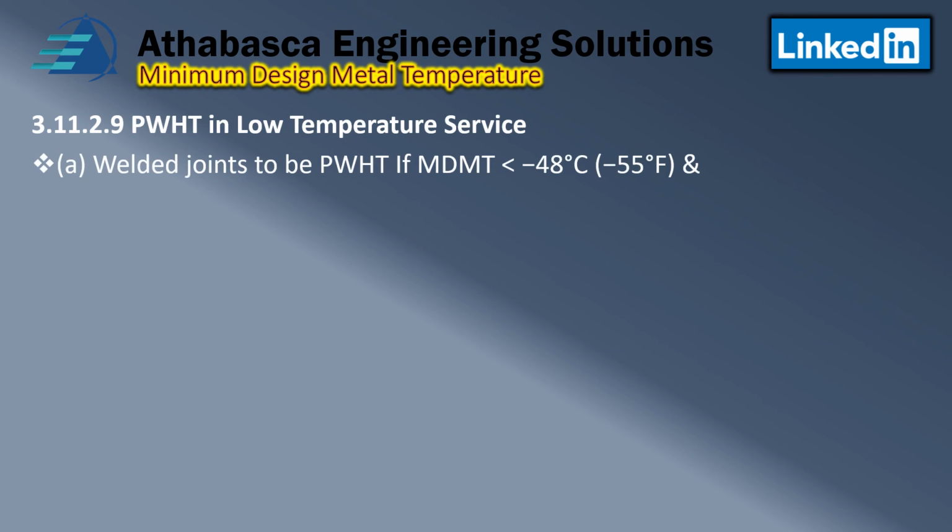Let's look at 3.11.2.9, post-weld heat treatment at low temperatures. So welded joints are required to be post-weld heat treated if the MDMT is less than 48 degrees Fahrenheit, and we have a class ratio of Class 1 with the stress ratio greater than 0.3.